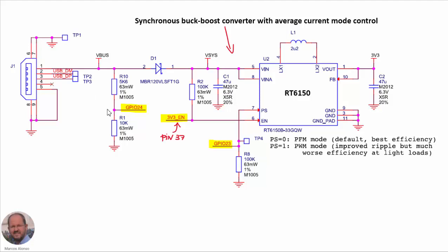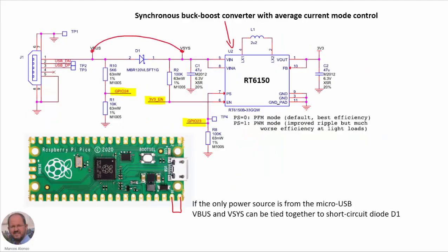And if we have a high voltage here, then this means that we have connected VBUS. So the microcontroller can recognize if there is any power supply connected to the micro USB connector. With this arrangement for the power supply, there are several possibilities to supply the microcontroller board. We are going to see some of them.